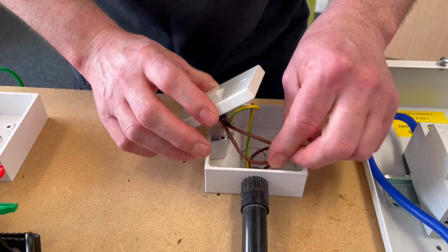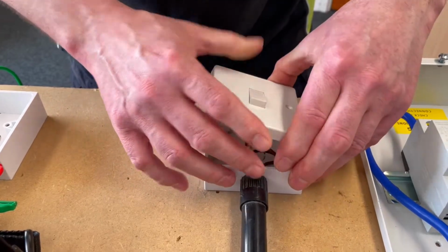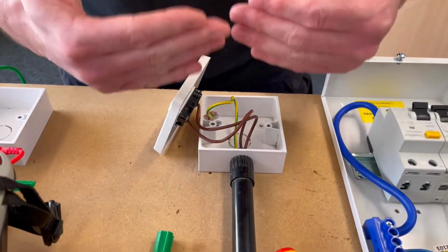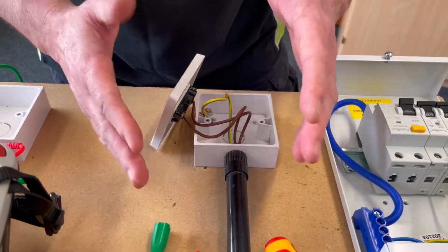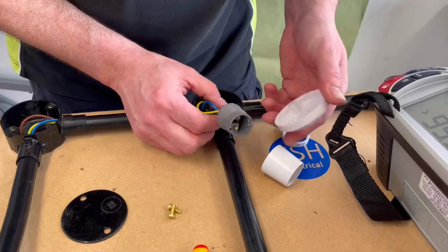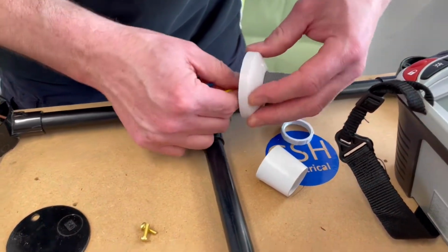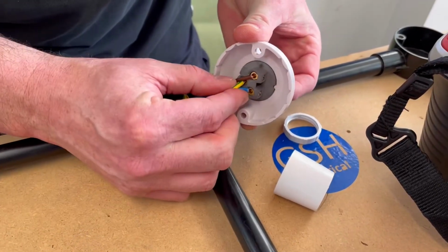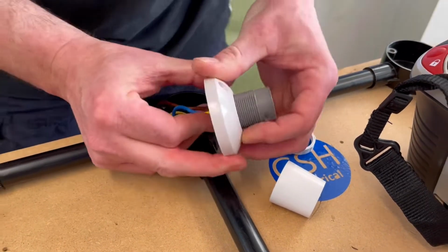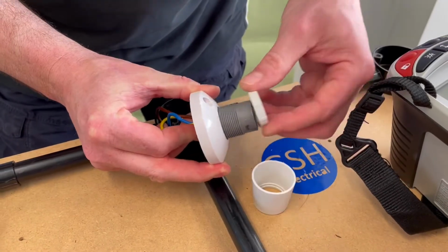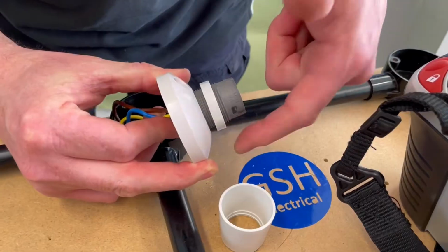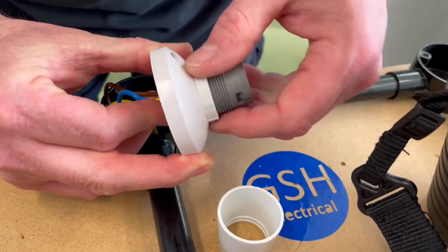I'm going to need to put all my covers back on. So I need to put all these back into position and rebuild my straight skirted batten lamp holder so everything can go back into place before we carry out our insulation resistance test next. So let's rebuild our straight skirted batten lamp holder. We put it in, it goes into one position, it actually locks in there. There's two little sort of keyways that mean it sits firmly into position. So base plate on first, followed by our ring. Just make sure it winds down nice and easily so you can see that it spins easily so there's no cross threading going on there.